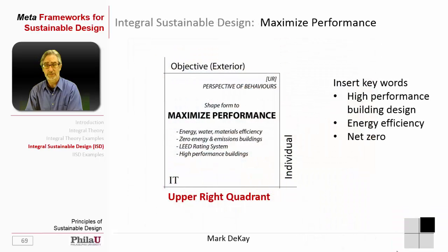So I would ask, for example, what is the performance of that building? Is it a net zero energy building? Probably not. Does it matter? Maybe. If my goal is to have a zero impact on the environment or even regenerate the environment, I know that beauty and experience has to be only one of the variables in the generation of design. So I'm looking at net zero water, net zero energy. I'm looking at high performance buildings. I'm going to use the LEED rating system here.